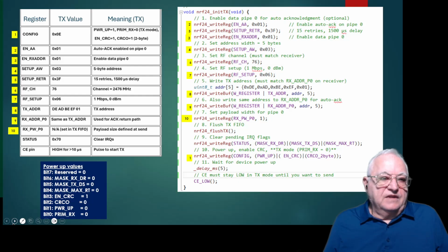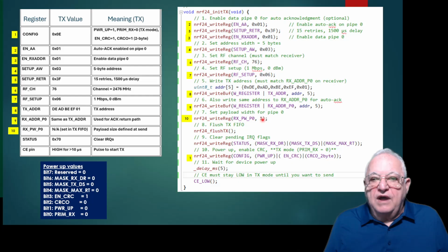Write to pipe 0. Usually you would put the number when you're going to actually do the writing, but in this case we have just one element, we're sending one byte at a time, so I just put it there for simplicity.